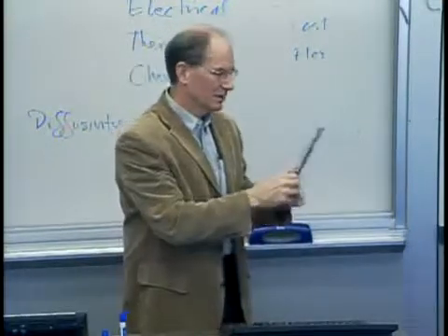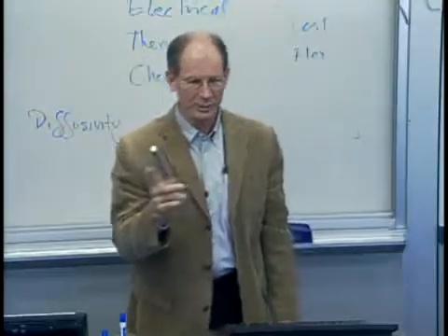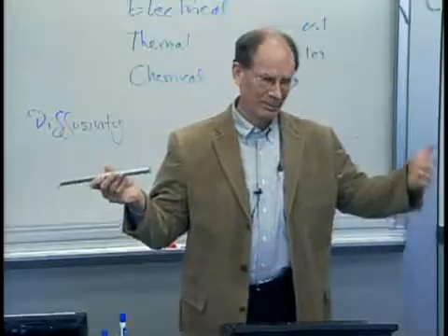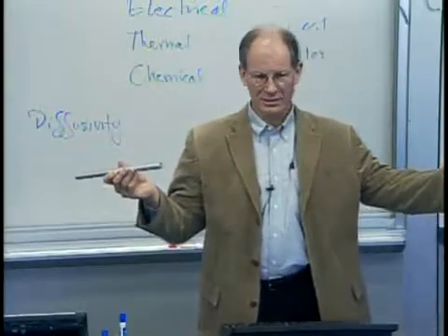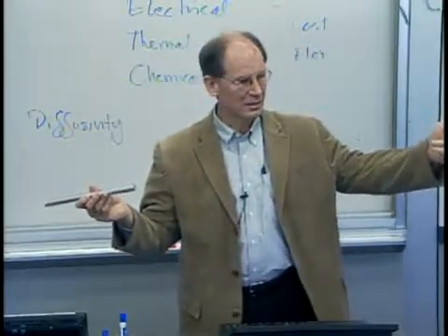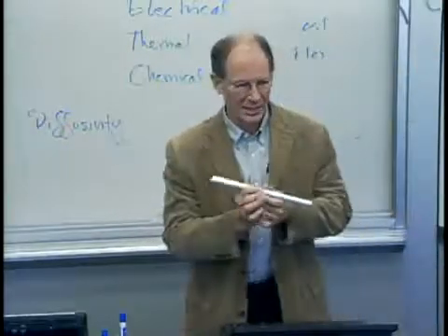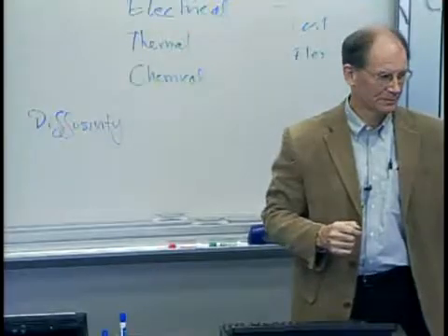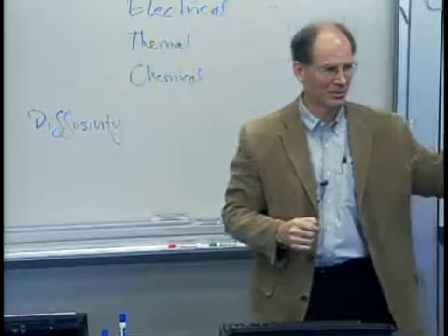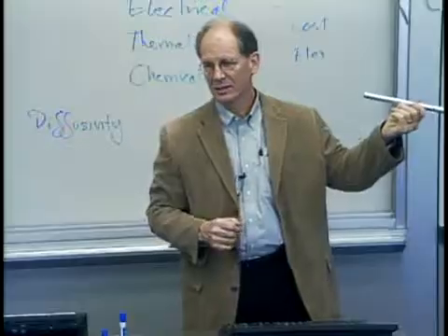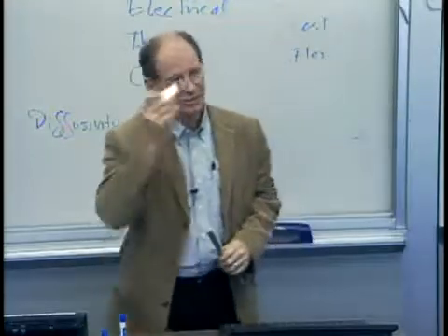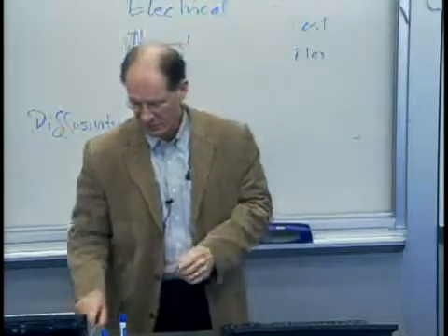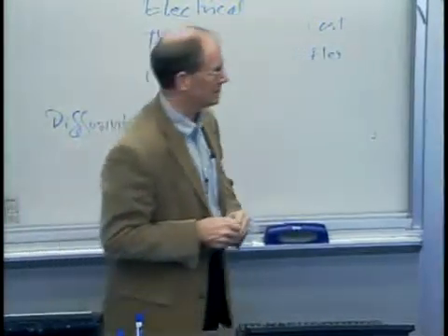But if I just say, well, here's a piece of aluminum, we did it in this mill over here, and it came out with the following properties: its elasticity, its yield strength, its strain hardening characteristics, and then I get supposedly the same material from a different mill, and they're 10% different. Not the elasticity, by the way, but all the others. 10% different. Huge difference here. Virtually no difference for the machining. So there's an inherent sensitivity of the processes to that.